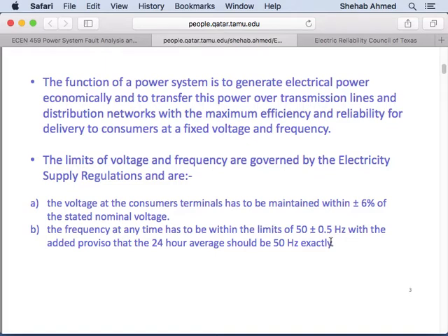And it's actually a blessing that this physics happens, because when the generator slows down, it's because it's loaded. If it slows down because it's loaded, then what's going to happen? Another generator that's not loaded will pick up the rest of the load. It's like